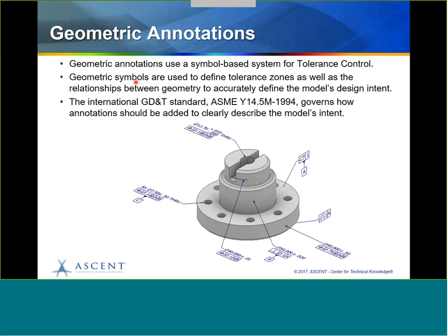This is all done with the GD&T. This is a symbol-based system for tolerance control. It's not something Autodesk has developed. It's an international GD&T standard. It is governed by the ASME standard Y14.5M 1994, and it governs how all of these annotations should be added to clearly describe your model's design intent.